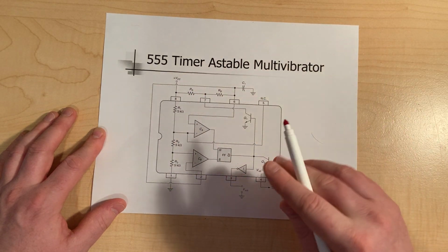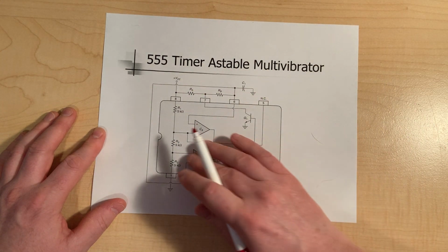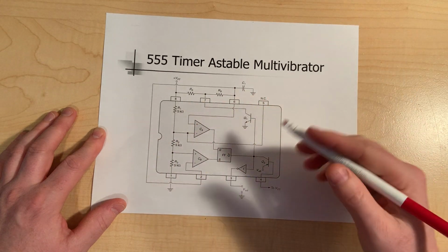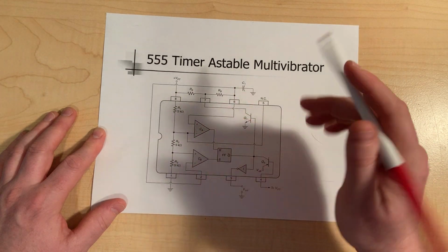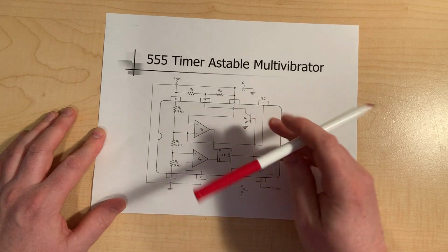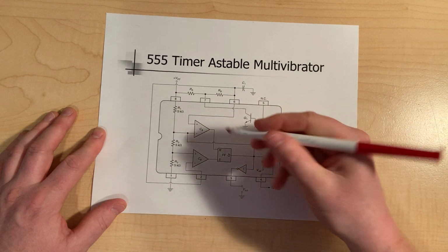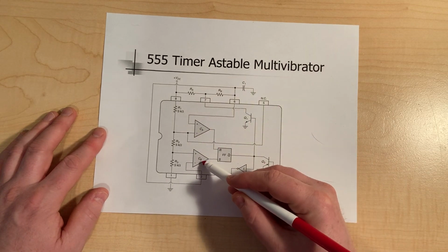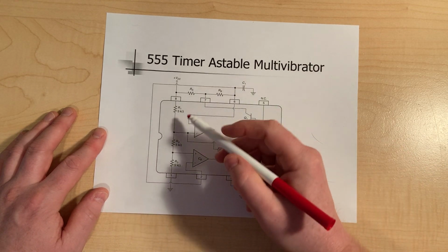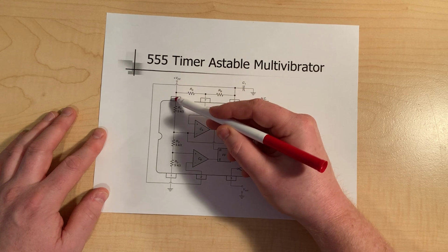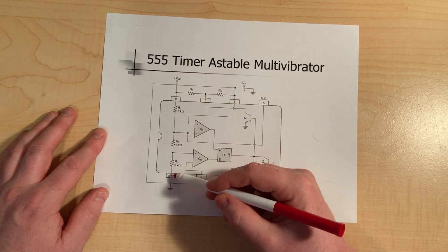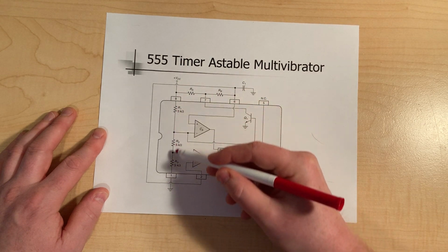So let's talk about some of the main components, what's going on inside the 555 timer. For all intents and purposes, what we have is two comparator circuits, comparator CA right here and comparator CB. You can see here from the voltage going to pin 8 all the way to pin 1 tied to ground, what we have is just a voltage divider.